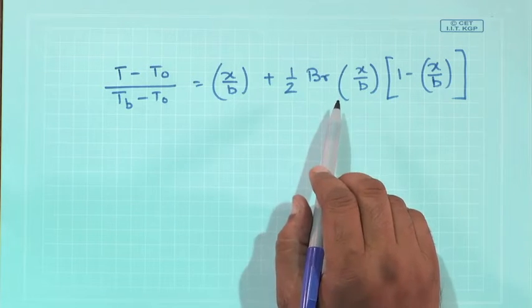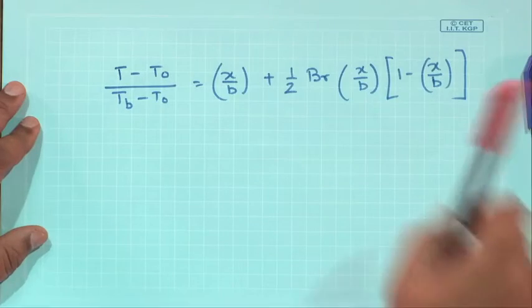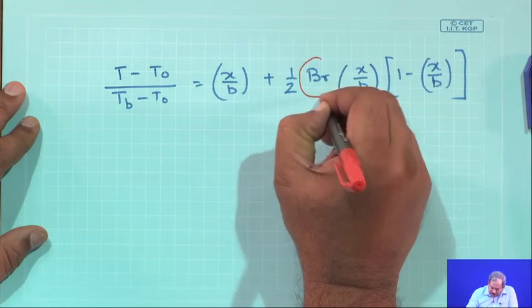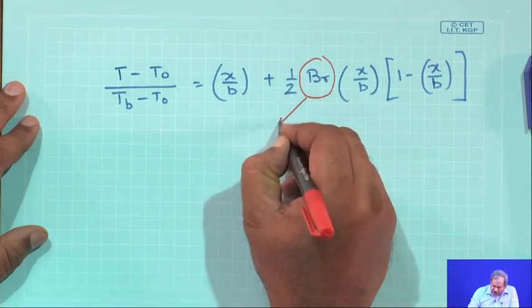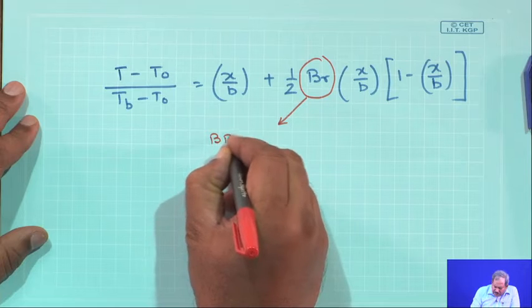It is extremely important to practice these so that you do not make any silly mistakes. So, you have a straightforward equation, two integration constants, two boundary conditions. So, evaluate C1 and C2 in order to get the form of the expression which I have written over here. Now, this Br is very interesting. This Br is known as Brinkmann number.